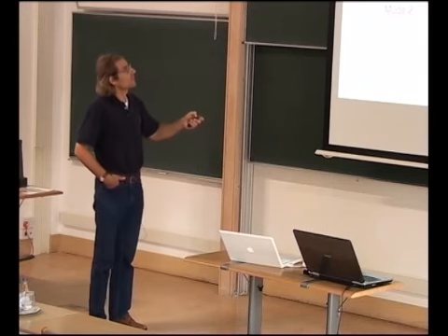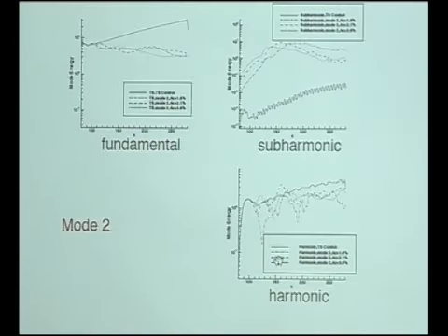And so I guess this is the last result I'll show you. This is the sort of explanation for why mode 2 seems to delay transition at higher amplitude. This is what the Tollmien-Schlichting wave would do by itself. When you put in the continuous mode, it's well known that it suppresses the growth of Tollmien-Schlichting waves. It's not contributing to Tollmien-Schlichting waves, it actually suppresses the growth rate. And this is a spectrum to show that it actually gets suppressed.